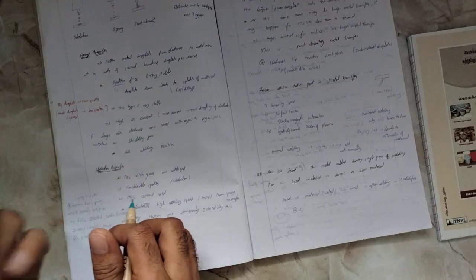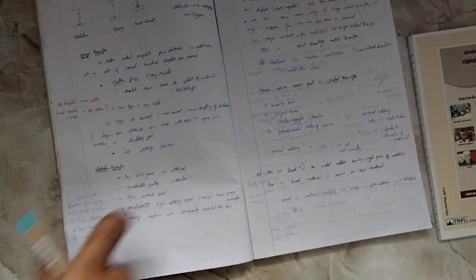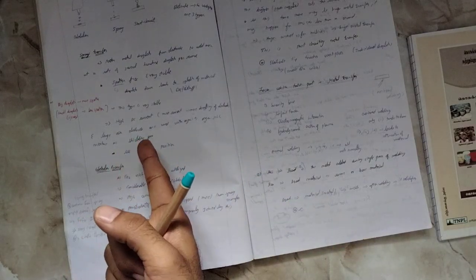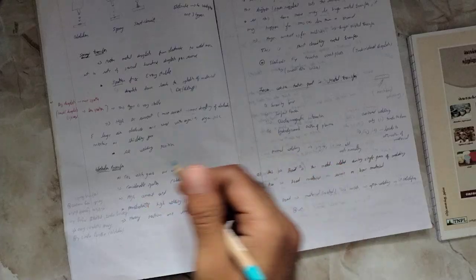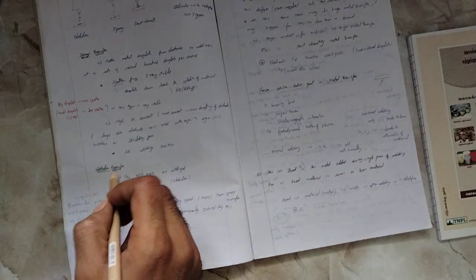So this is a kind of spray transfer. In the spray transfer, generally the shielding gas is used, and this type of arc is very much stable, with high DC current, more current. Large electrodes are used with the argon shielding gas. Next, you can see carbon dioxide rich gas is utilized, definitely for globular transfer.